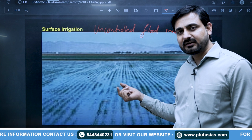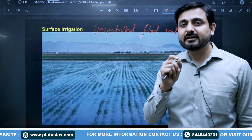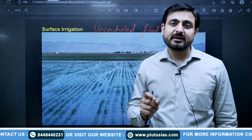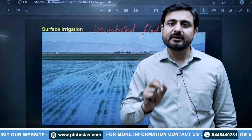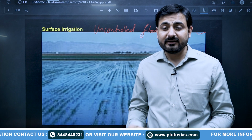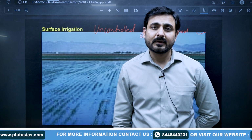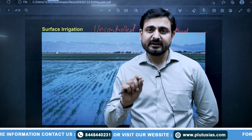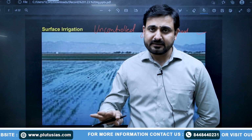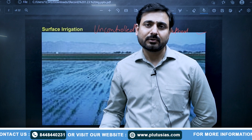Huge amounts of water are likely to be sucked up. It is not suitable, especially in regions with arid or semi-arid soil, where there is more porosity. Means the soil is very porous and the water is likely to be finished all of a sudden, within a very short time period. It is also not suitable, especially for depth of irrigation at different regions, when the field is not leveled. Leveling of land is not followed.